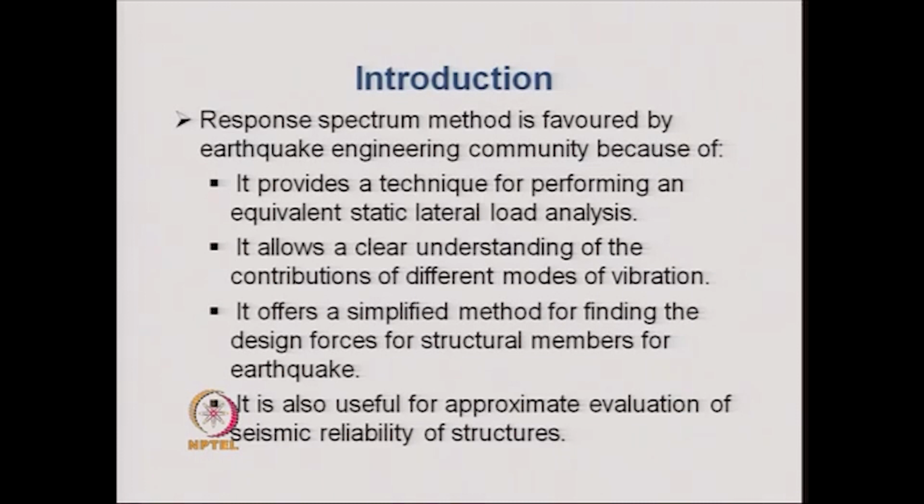Secondly, it allows a clear understanding of the contributions of different modes of vibration. That is another thing which a designer would like to understand: as the structure vibrates in different modes under an irregular time history of excitation, one would like to understand the contributions of the different modes of vibration in the structure.